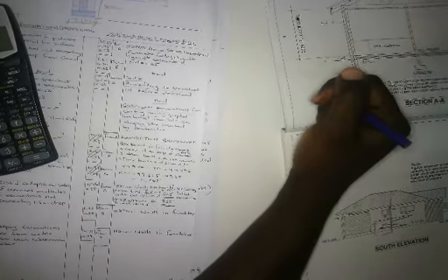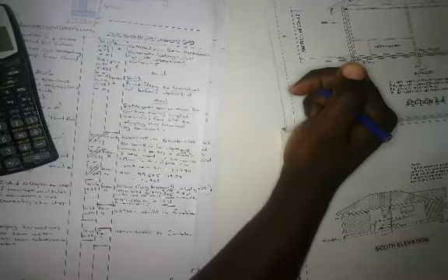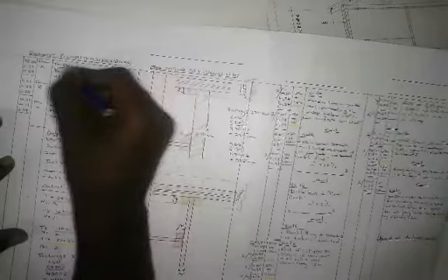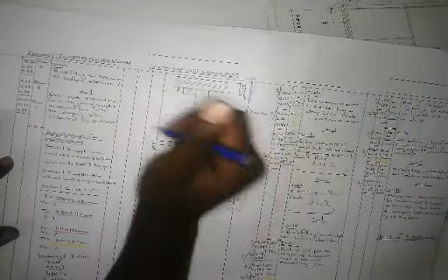From there we say 270 cavity wall, including wire ties and filled solid with unreinforced concrete, 10 MPa. That is the description for your 270 cavity wall. Then you go again to your centre line, 35.56. It will always be the same, times 0.84, which is your depth. Do the same for your 230 wall and the same for your 110 wall.